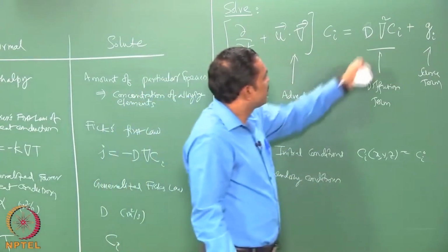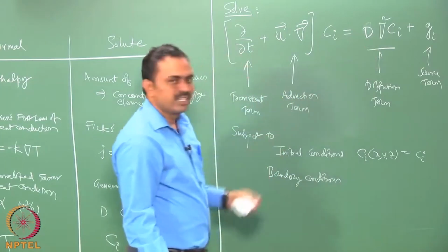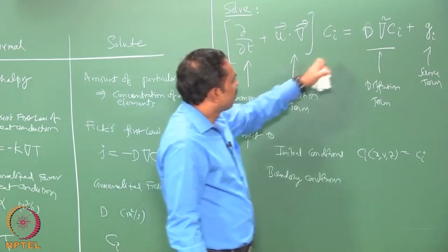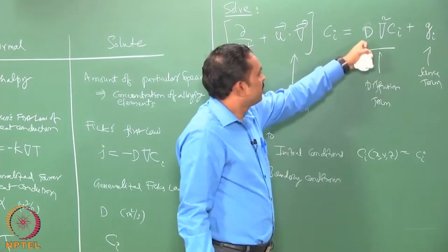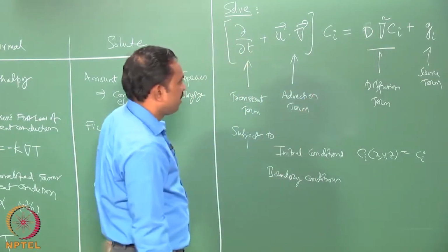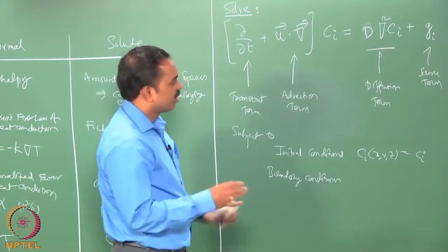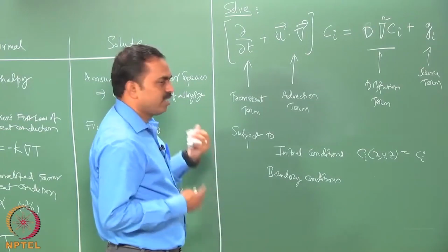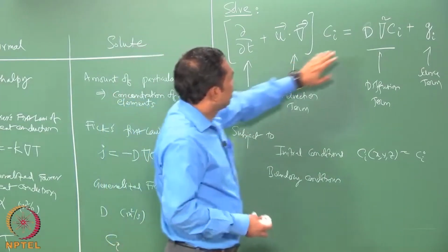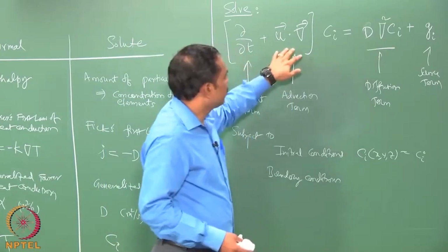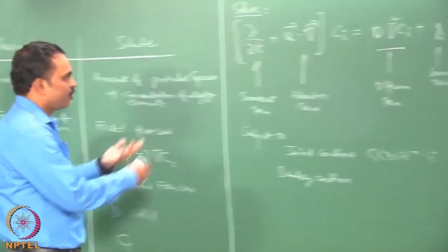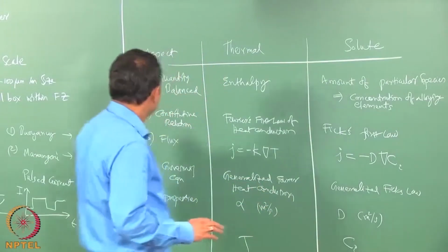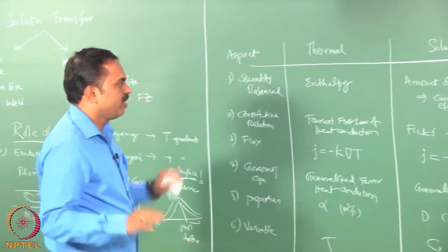And we already have mentioned that the diffusivity is very weak in the solutal conditions, that is the solute diffusivity in a liquid is a very small value compared to the thermal field. The thermal diffusivity is generally 4 orders of magnitude larger than solute diffusivity. So, because of that this is weak and this is very strong, and it is also fluctuating. In other words, the distribution of solute within the domain is governed primarily by the convection pattern, and it is going to be well mixed.